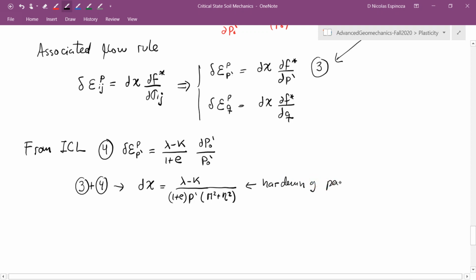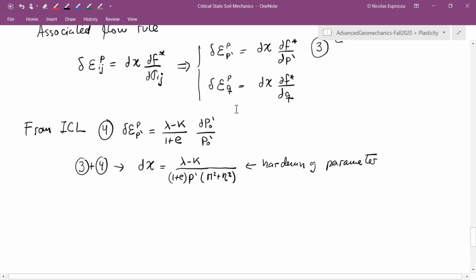All right, so this is the last step in calculating these plastic strains. Let me go ahead and write those directly as matrices, so I also save some space. Similar to what we did before, we have the volumetric plastic component here, and the deviatoric plastic component as the second element of this column vector.